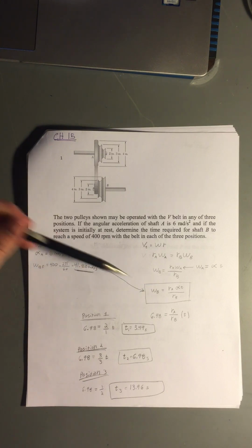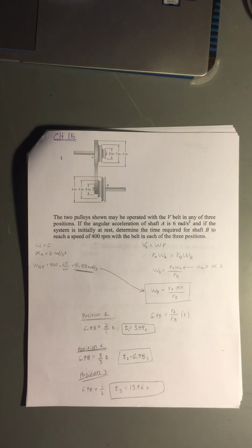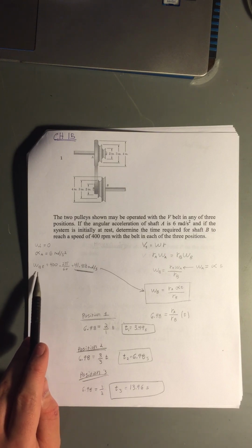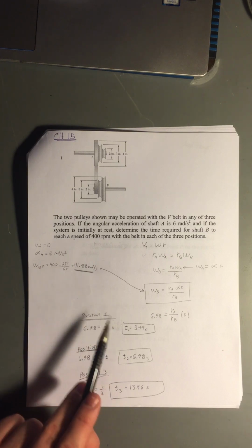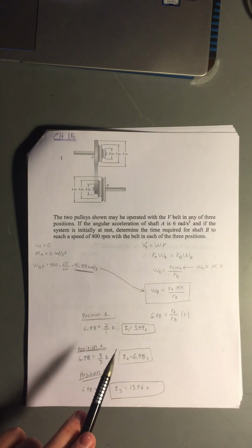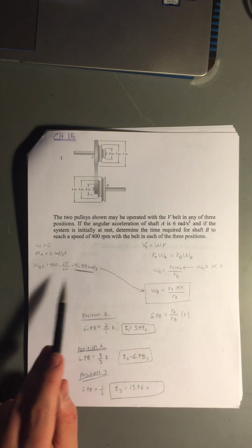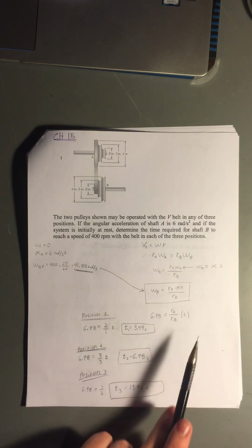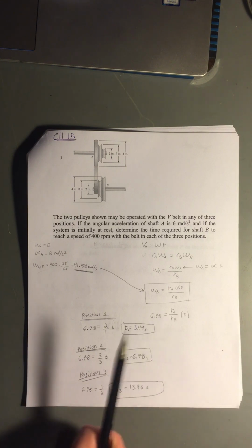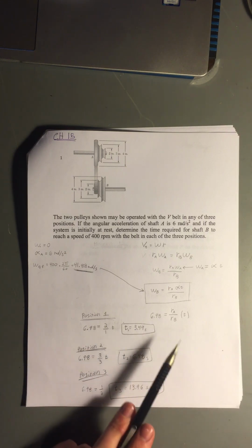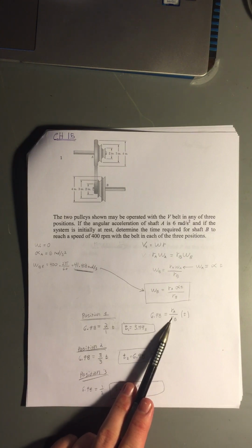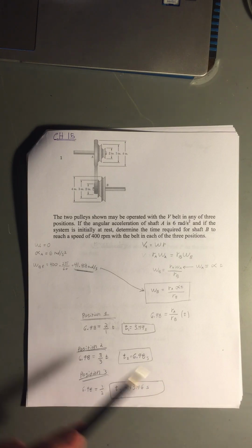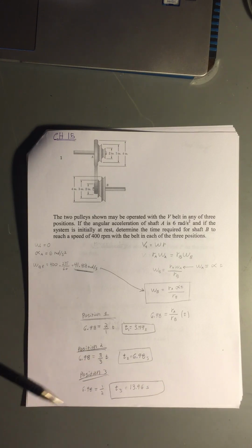We can divide omega by alpha to give us this term. Our omega value here was given to us in RPM, so we had to multiply by 2 pi over 60 to turn that into radians per second. Then we take this omega term and divide it by alpha to get 6.98. Then we have this really nice equation that relates the radius of A over the radius of B times t, which has to equal the 6.98, which is the omega that we're looking for, omega B.